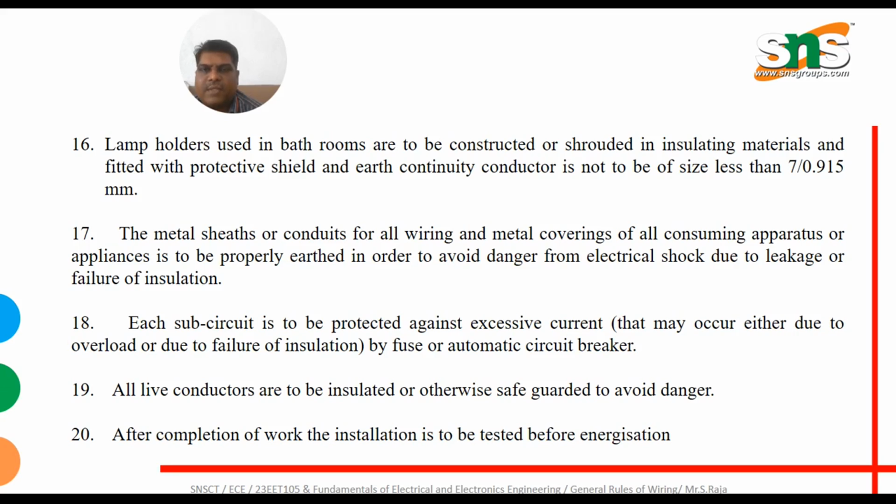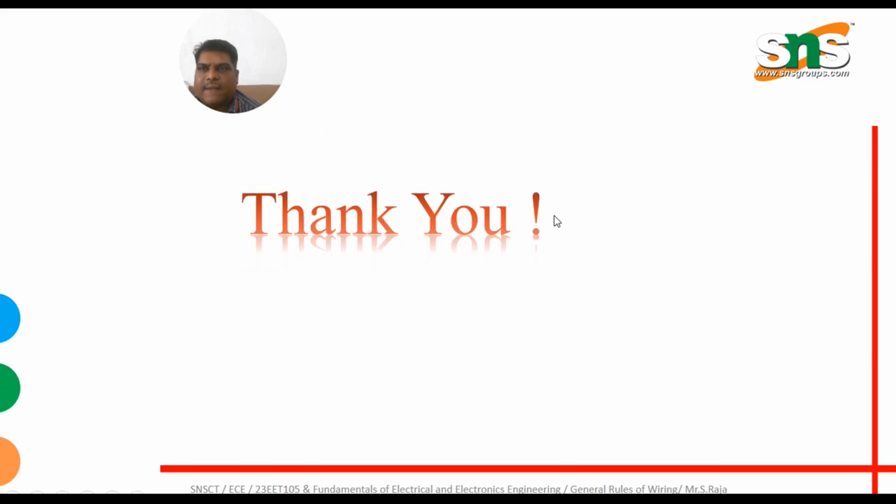Each sub-circuit is to be protected against excessive current by a fuse or automatic circuit breaker. So the purpose of the fuse or automatic circuit breaker is to interrupt the excessive current. All live conductors have to be installed or otherwise safeguarded to avoid danger. After completion of work, the installation is to be tested before energization.